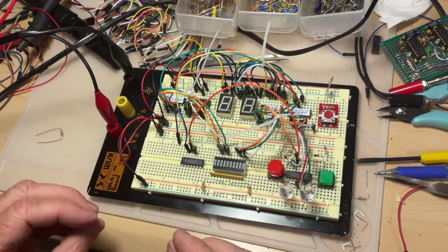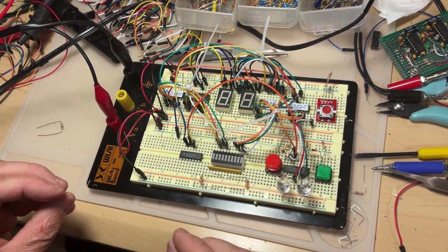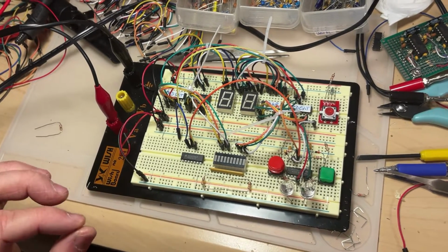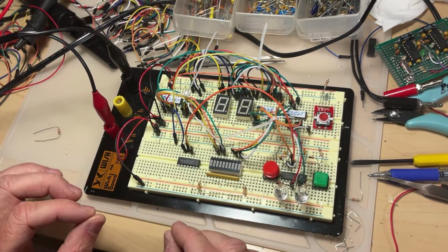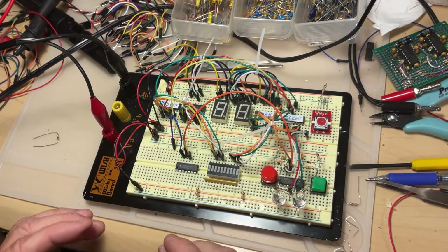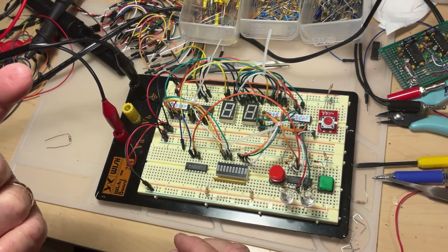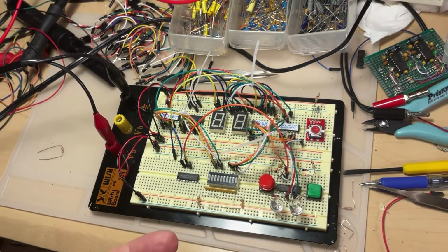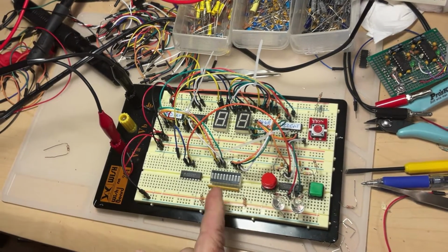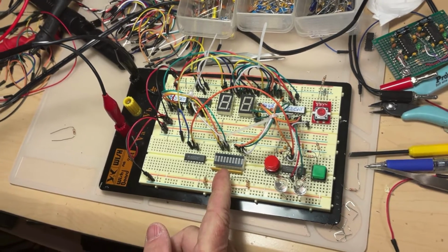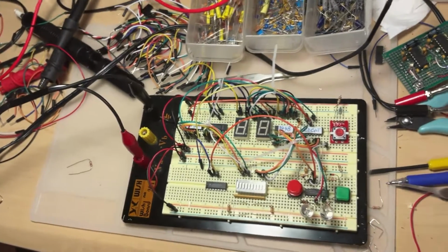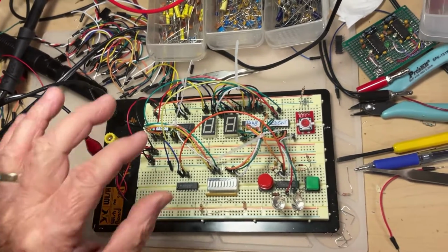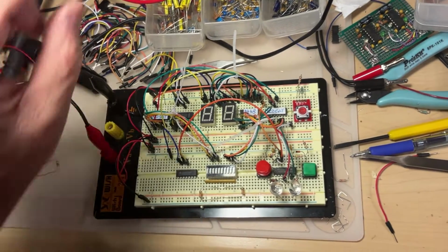So one of the nice applications of the 555 is what we call a power on reset. What does it mean? In the moment you apply the power, one simple 555 is going to apply shortly a pulse to the reset of the counter, and this way the counter will show you 0, 0 from the beginning.